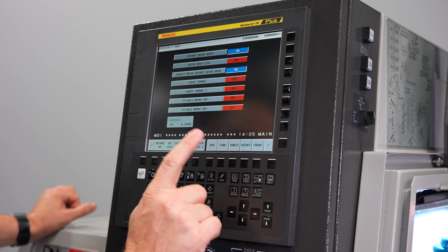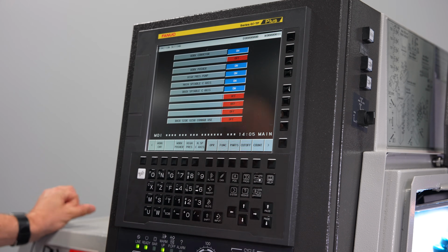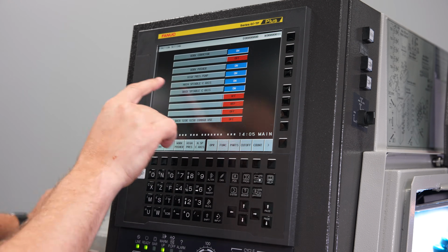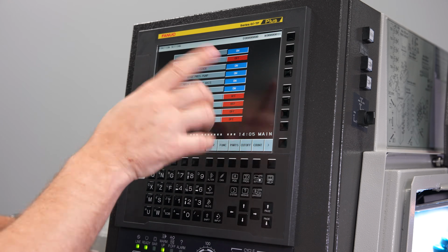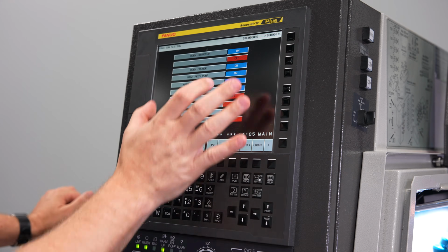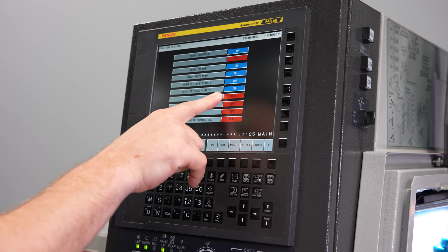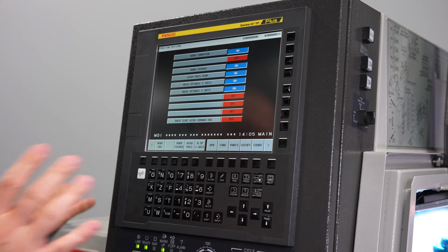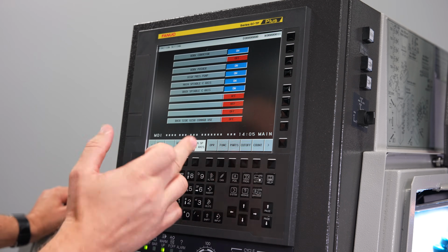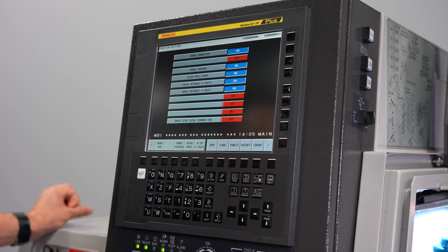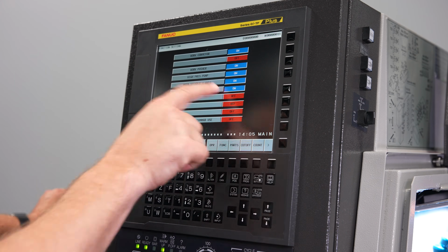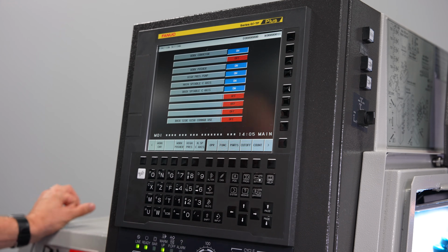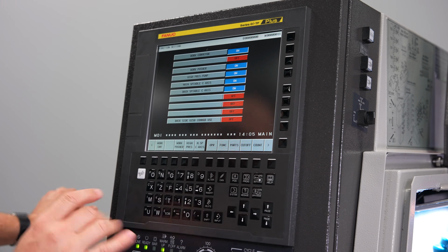So, the function settings screen, same thing. We have our work conveyor, we have our work pusher, high pressure pump, all that's the same. However, you'll see main spindle C-axis, back spindle C-axis, they're both on, and those will always stay on. You can turn it off if you wanted to, but Tsugami America brings in machines to North America with full C-axis on main and back spindle all the time, so you'll see this is on. I don't see any reason why you would ever want to turn it off. It's just an option in other places globally.